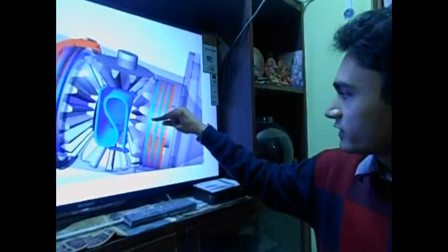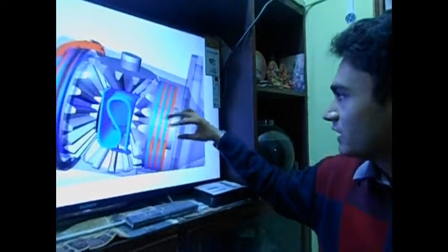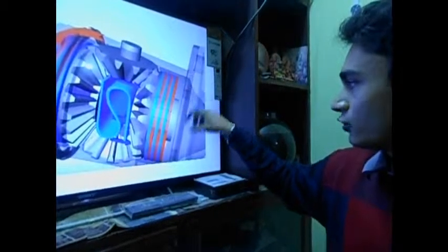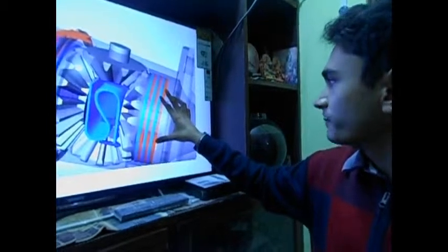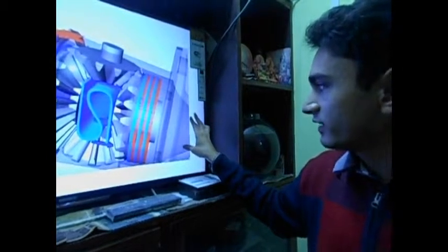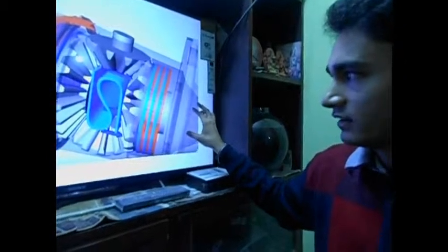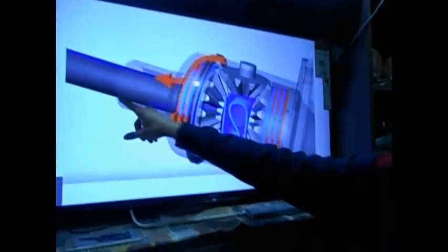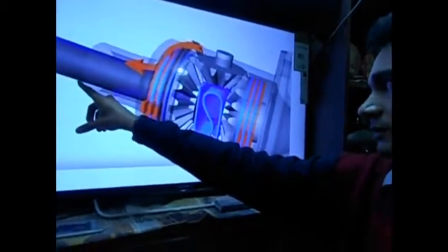However, if there is more reaction on the right hand side, then there is restoring force coming from the right. This tends to lock the clutch plates together by compressing them. If the clutch plates are locked, then the differential housing rotates along with the clutch plates. Since the grip is higher on this side, it is desirable that this side should rotate. However, on this side, we do not have much resistance to the movement.